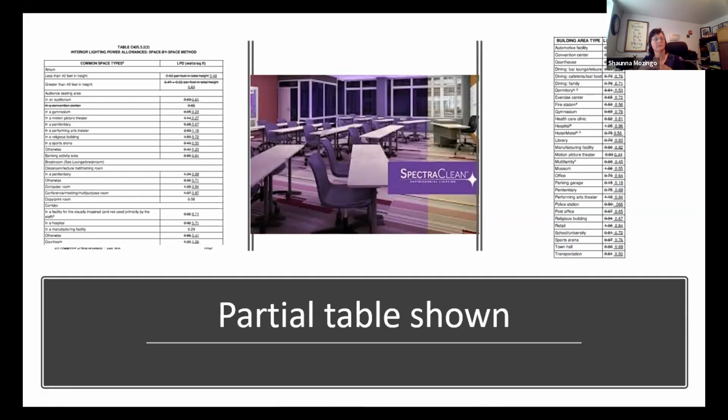So there's an exception, number 20 now, for all the lighting that doesn't have to be counted into your general lighting wattages per square foot. That kind of lighting doesn't have to be counted into your calculations. So that's a new exception that got added.